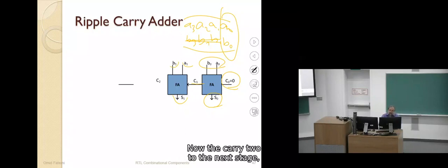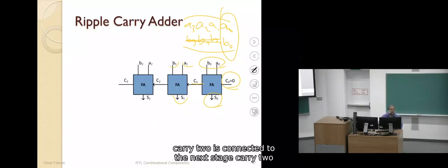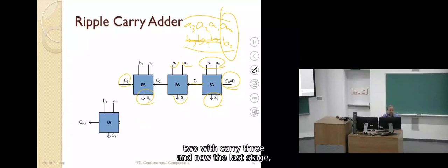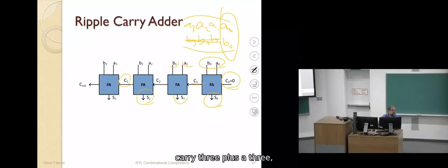Now we connect carry 2 to the next stage. Carry 2 plus A2 plus B2 outputs S2 with carry 3. And now the last stage, carry 3 plus A3 and B3 produces S3 and the carry out. Here carry out is carry 3, the last bit. So carry 3 is the carry out.